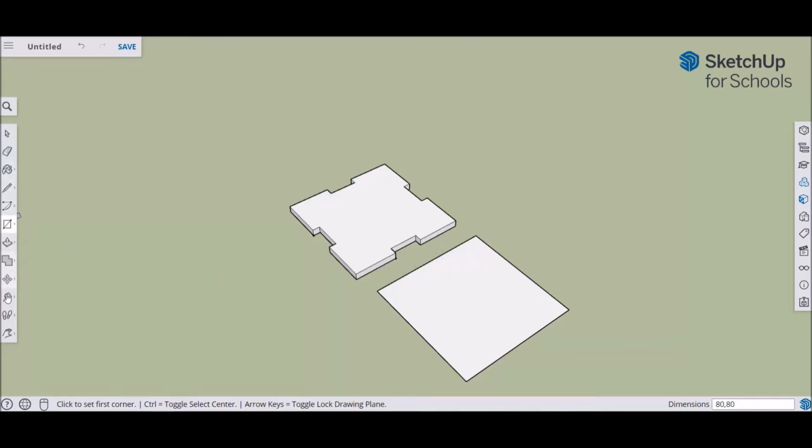So I've got to get my tape measure, and I want to get rid of this bit off my side, so I need to click my endpoint and go along to tell it to snap next there, 30 millimeters, make a mark, take my rectangle. I want to go from that guide point over to this side here. I want that to be 30 by 5, center.